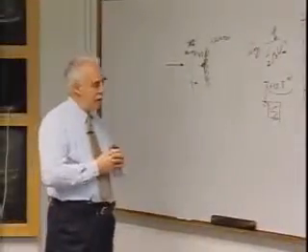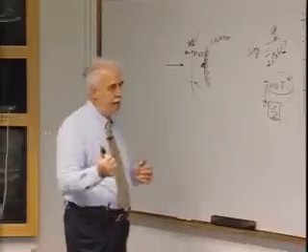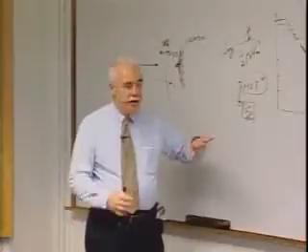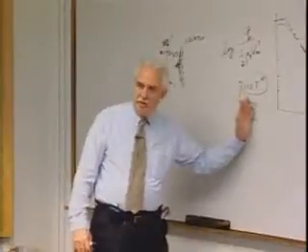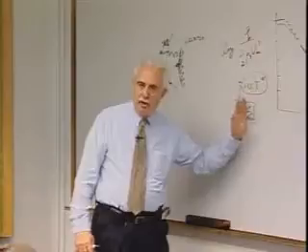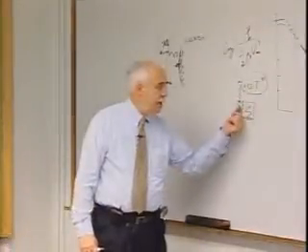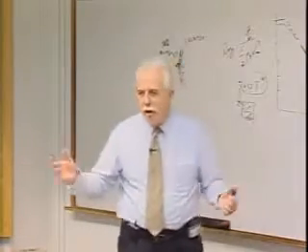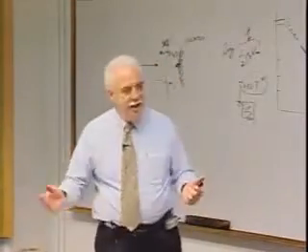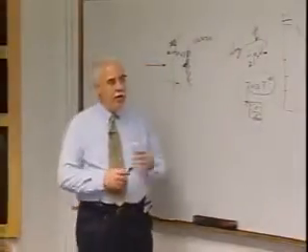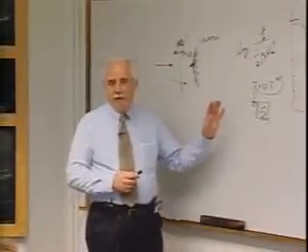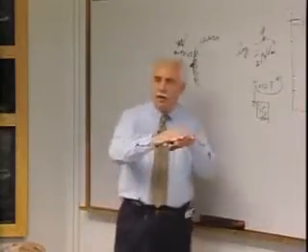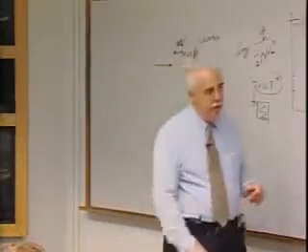Now, while I'm on that, the ablators were developed for capsules, and we kept getting lower and lower density because we wanted to minimize the diffusion of energy from the surface in. There needed to be a substantive enough surface to hang together. If you just have charcoal and blow on it, it's not going to stay there. With the early capsule, with the Apollo, we had a fiberglass structure in there that basically retarded the ablator from flowing away.